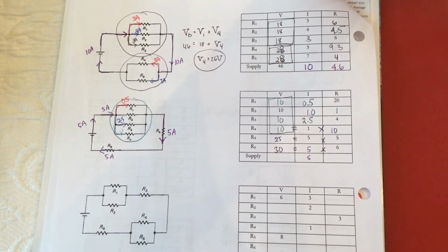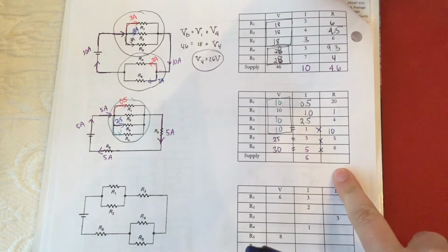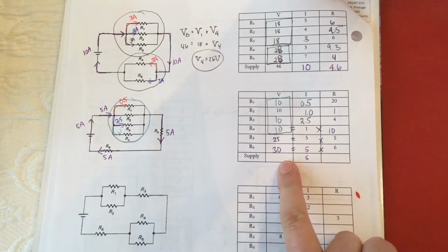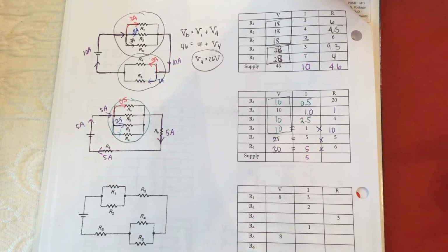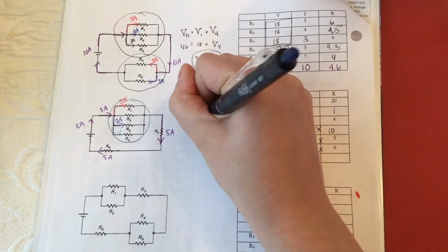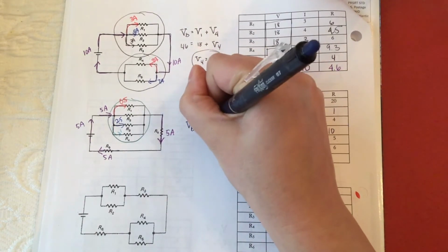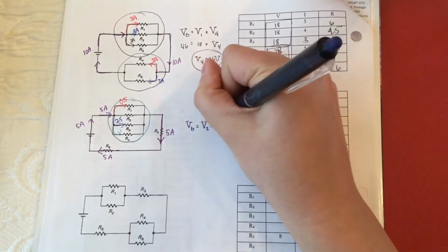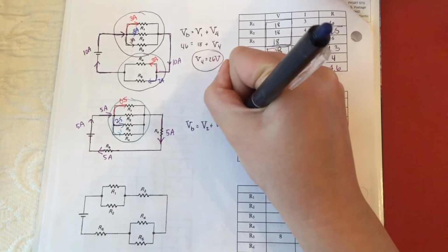And so you have a choice here. If you know how to calculate equivalent resistance, you can do that method. But it's probably faster to do the loop law to determine the supply voltage and divide across. So I'm going to pick any closed loop that starts and ends at the battery. So let's say it goes from R2 to R5 to R6.